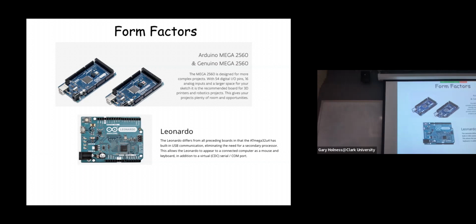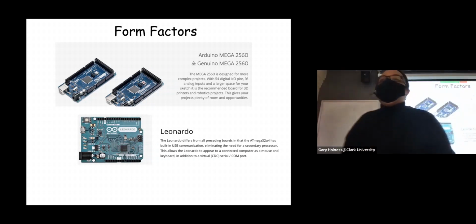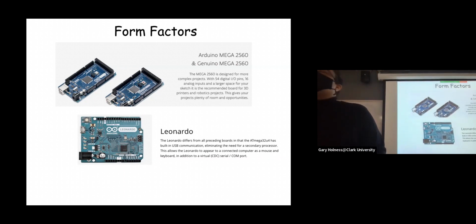I'd have one for my elbow. I'd have one, 2, and rotate for my wrist, another 3, and then the 7th one to make my hand open and close. And that's even with just a basic gripper, if I had fingers, it'd be even more complex. And so with all of those motors, you're going to need to control each one in a coordinated fashion to get the motions that you need for a complex mechanism like a robot arm.